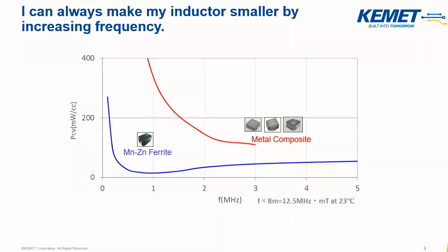And if we take a look at magnetics, one of the big issues is core loss. And as you go up in frequency, the materials that are used to basically increase the magnetic field going through them, which increases the permeability of the component, as those tend to get higher in terms of increasing permeability, they also tend to get lossier as you go up in frequency.